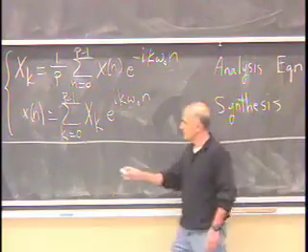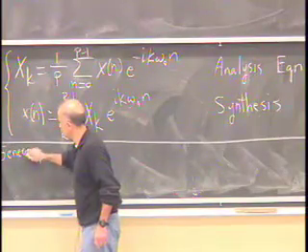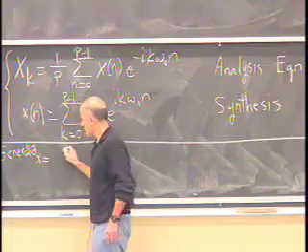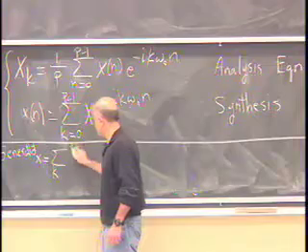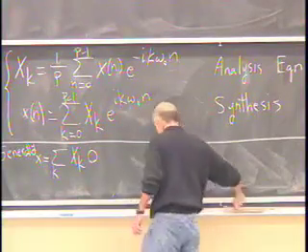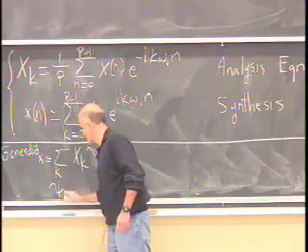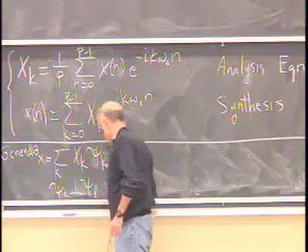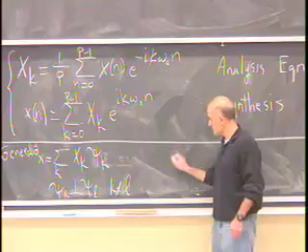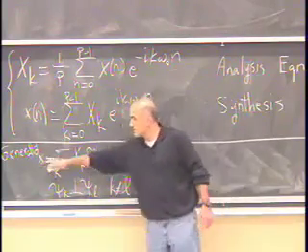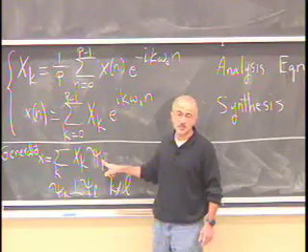In general, whenever you have to expand a signal or a vector in terms of a linear combination of a bunch of other vectors that are mutually orthogonal, to find the kth coefficient, you simply take the inner product of both sides with the kth signal or kth vector.